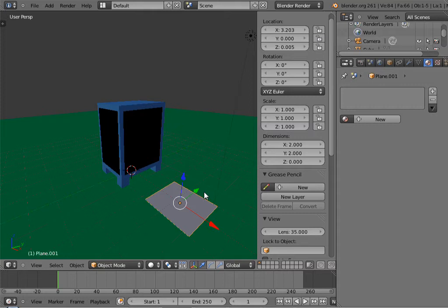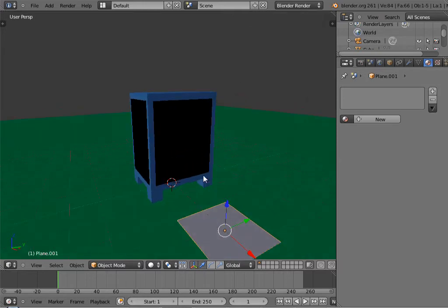Now, really, if you were going to do this, you should probably make it an actual box that's got some height, because a real pavement will have like a curb, but sidewalk, whatever. I'm trying to make this international. But yeah, that should look decent, and if it's still a bit of a problem, we can always take it up a few notches more, but 0.005 should be good enough, I think. Press N to get rid of that again.